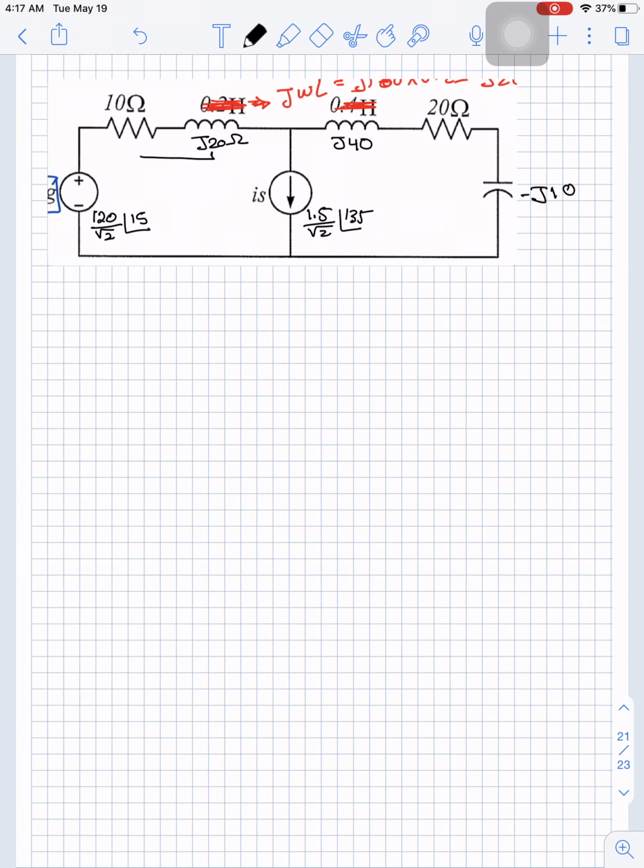Now these two values are in ohm, and if you have two elements sharing the same current, they are connected in series, so we can add these two together. We will use a box symbol to represent an impedance, and impedance means a mix of RLC. Whenever you have an RLC mix, you sketch it as a box. Inside this box there is a mix of elements.